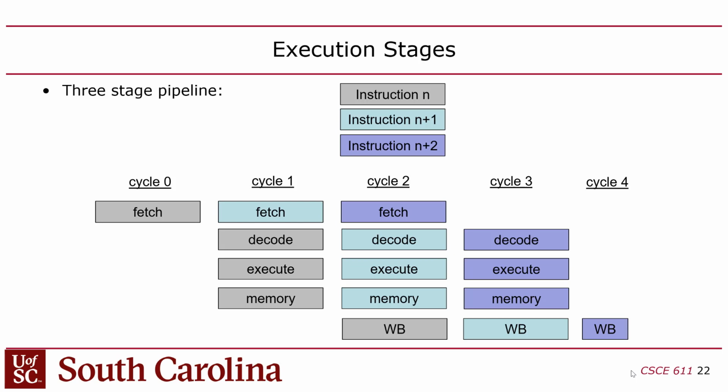You guys with me? Okay, so it's basically just keep track of what signals are in which stage and delay values from one stage to the next when you need to. Because just putting a plain old register that says always_ff at posedge clock, new value equals old value, will effectively push a value from one cycle to the next.